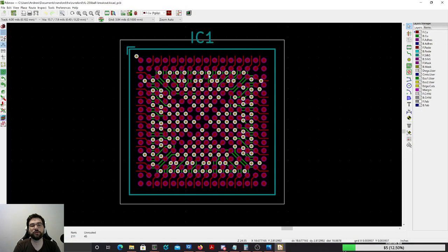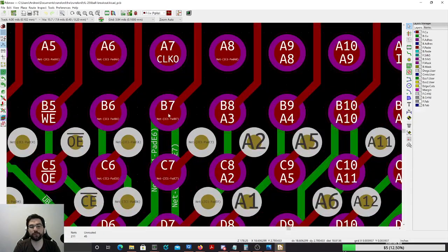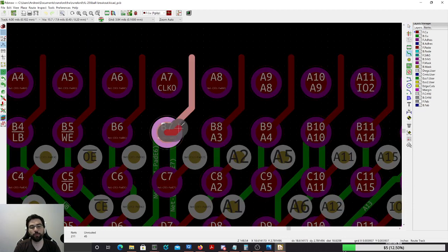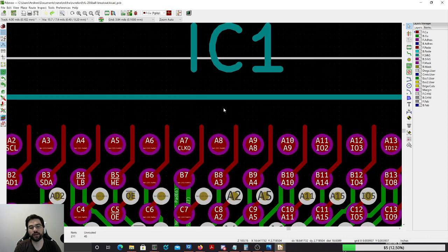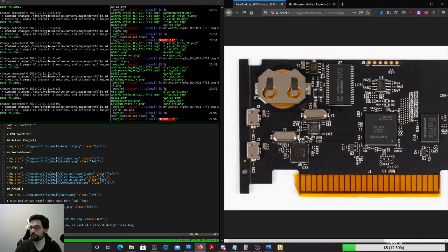So when you're routing a circuit board, you need to be able to get signals out without hitting other signals, basically. And so that's where you break the traces out from the array, right? You end up with something that looks kind of like this, where you have all these vias and all these traces, so that you can get at the signals even on those inner balls and route them out to other areas of the board. So breakout. That's what Dub was talking about. Did that make sense?